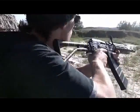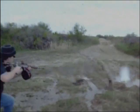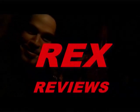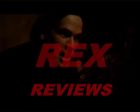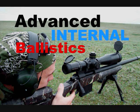So again, I should probably reiterate that the secret to dealing with these harmonic and vibratory inconsistencies that affect the axis of your bore before the projectile leaves the muzzle, in internal ballistics like we're talking about here, is absolute consistency. And when we're talking about the rifle system itself, the main ways to solve those problems are to pay very close attention to make sure everything in the rifle is put together nice and solidly. Everything's mated up nice and tightly. You have no loose screws. You have a good quality stock that's not changing its bedding from shot to shot.